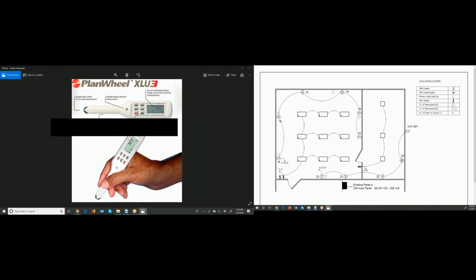You set the scale of the blueprints on the ScaleX. And then when you roll across the blueprints, it measures the length of conduit needed or the length of anything. So then the digital readout shows you the length that you need. And I use this again for taking off conduit. So there's two different main brands, ScaleX and ScaleMaster. They both work the same, and you don't need the expensive digital or Bluetooth versions, just a plain version. Okay, so I wanted to show you that tool. That's what you use for conduit takeoff.